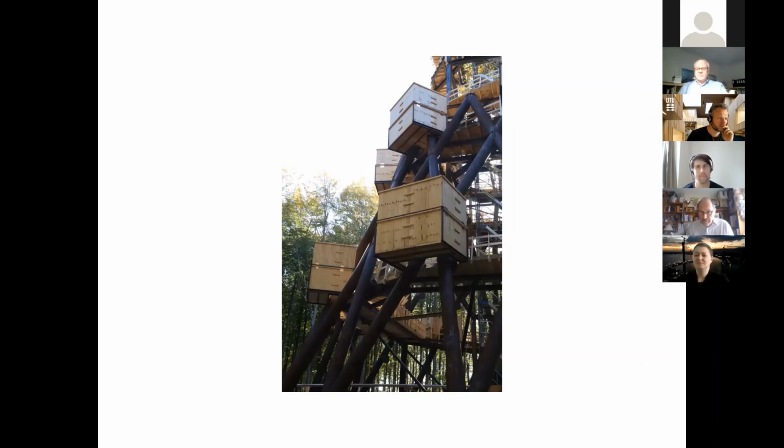Thanks for that comment, Andrew. But I would say, on top of that, when you are working with circular structures, you have to work with minus tolerances, not with plus tolerances. Then you create a problem. It's easier with a little bit of minus tolerance because you are normally in a position to solve that in the welding. But plus tolerances is very bad, which we also now and then experience.